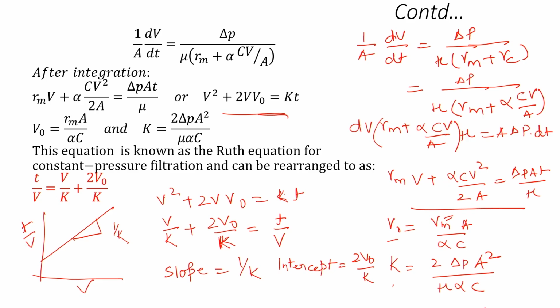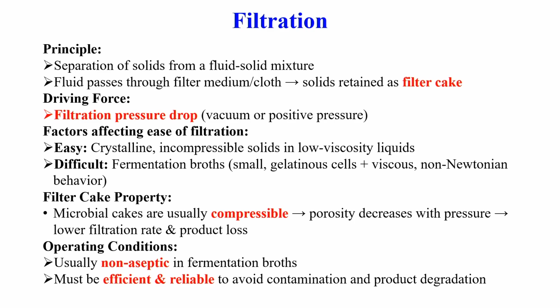medium resistance. So, what we discussed in filtration is that we are separating the solids from the solid-liquid mixture and flowing the process through the medium, and the solids retained are called the filter cake. The driving force is the filtration pressure drop delta P. What are the factors affecting filtration? If there are incompressible solids in a low viscosity fluid, or some crystalline material, they are easy to separate.